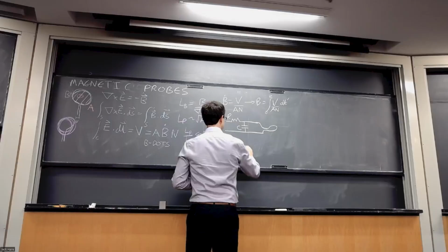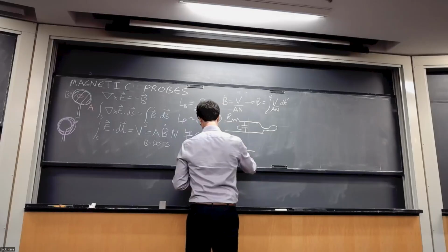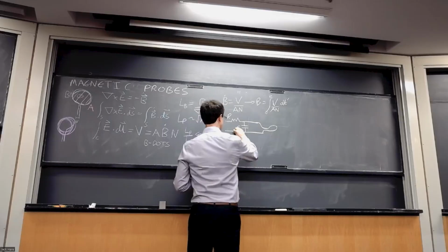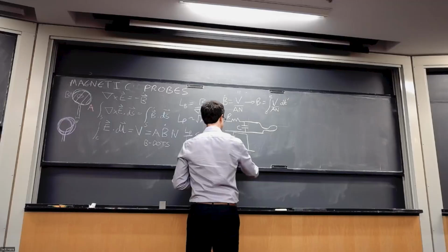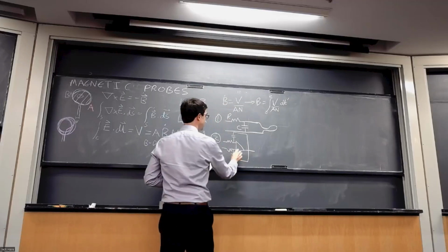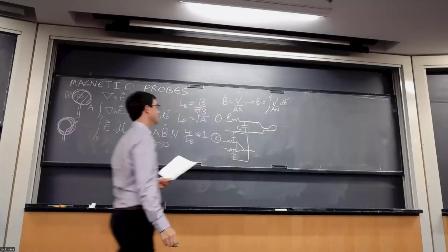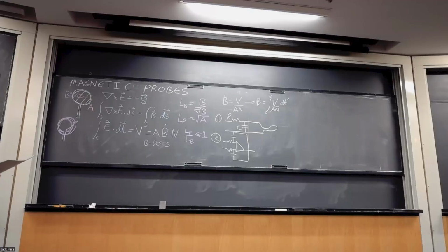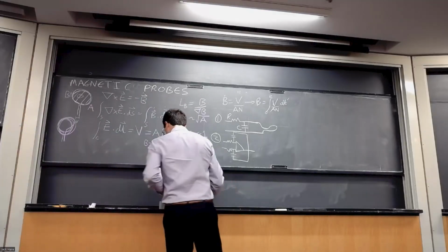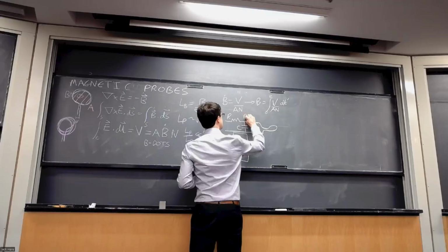So we can put an op-amp in here, and we can put in something where we have a resistor and a capacitor for each of the inputs. And this is nicer because, of course, it's going to buffer your signal as well. It makes it easier to do the impedance matching. So you might want to consider an active system like this. So just to be clear, this is passive.